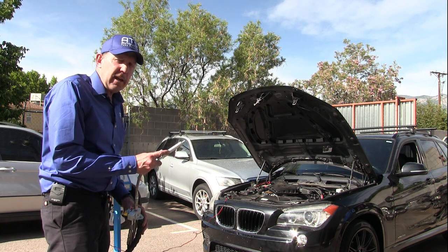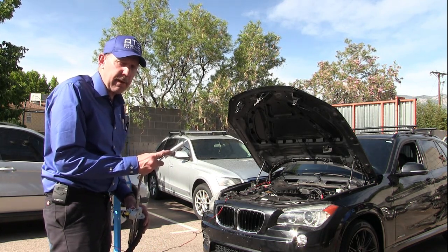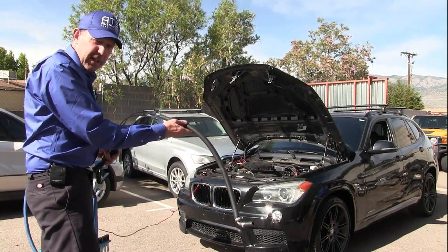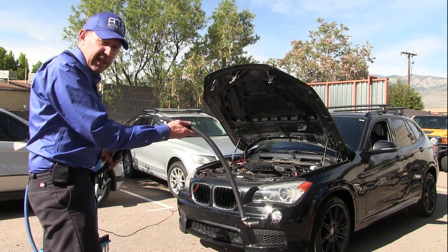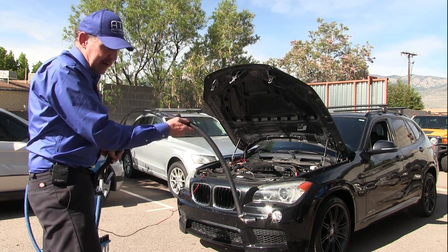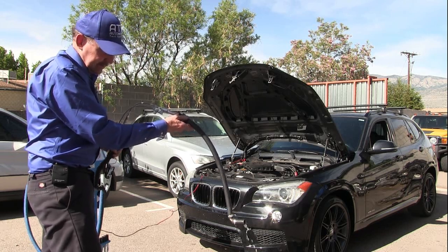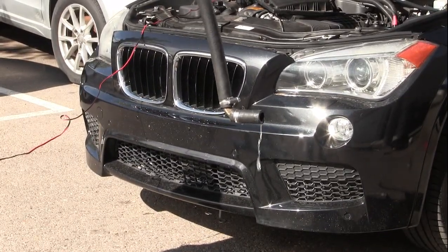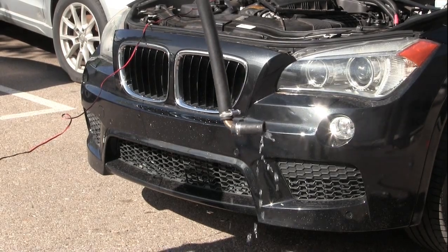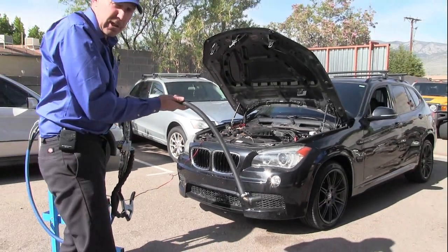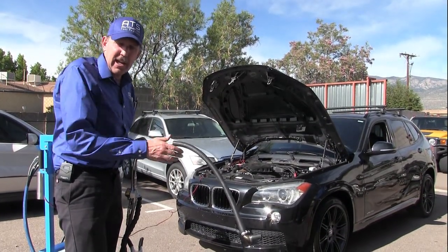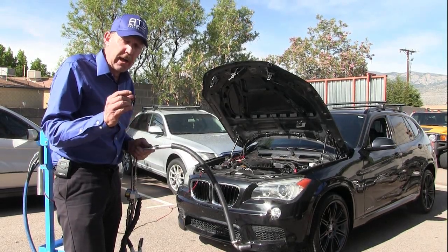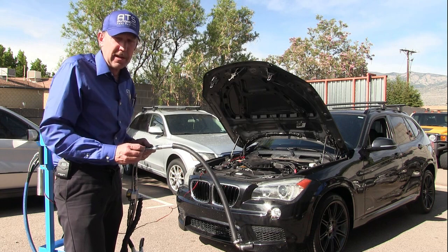Now let me demonstrate, if we use the wrong hose assembly, what's going to happen to your engine. Now we've just seen the fine mist that would come out of this nozzle, and it would be blown into the intake system of your vehicle. Now we're going to look at what happens with the wrong hose assembly. Do you see it just running out? Well, that liquid base is going to end up in your engine, and that can damage your engine or the catalytic converter. Again, I want to stress, we only use the ATS hoses directly coupled to the manifold of your induction system.